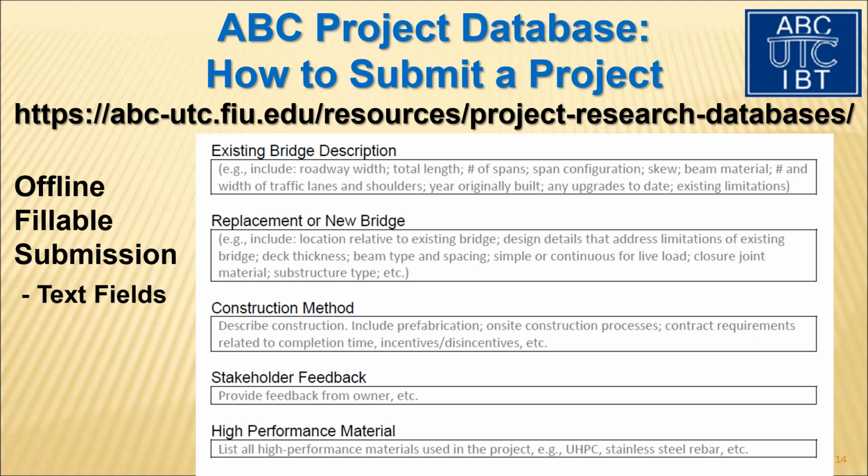For the existing bridge, information may include the bridge length and width, number of spans, span configuration, skew, beam material, number and width of traffic lanes and shoulders, the year originally built, any upgrades to date, and condition that led to the replacement or upgrade.